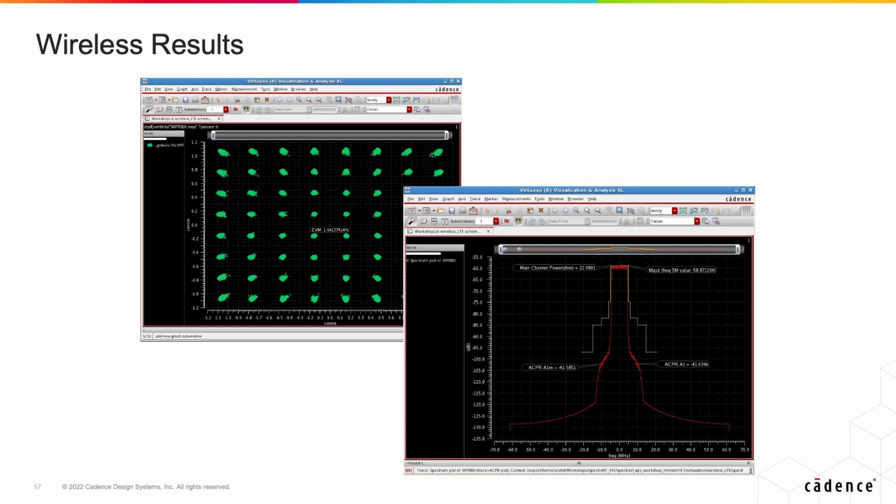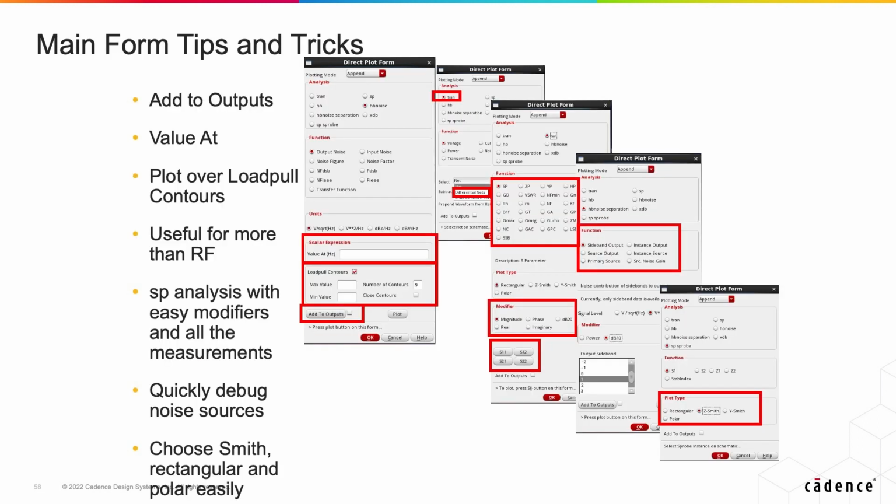If you are giving us your I and Q files, use the classic flow, then we can only give you power spectral density and ACPR, but we cannot give constellation because we really don't know the sequence.